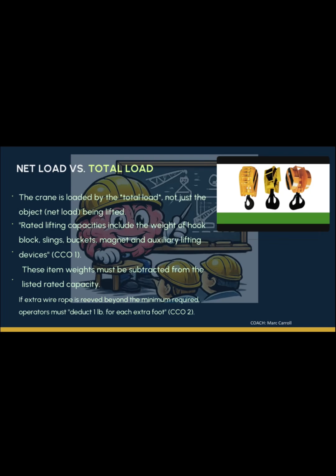Stability, anything below the black line. We also call that black line the tipping fulcrum. It's represented by capacities below the bold line. These are based on the crane's center of gravity. Ratings on fully extended outriggers do not exceed 85% of the tipping loads. If you're on rubber, it's 75% of your allowable line pull. And if you're on crawlers, it's 75% of your allowable line pull.